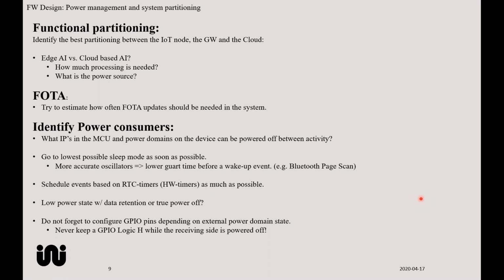So it makes a very big difference, and especially over years of operation, it makes a significant contribution to the overall power consumption. Now, these states will change depending on whether you enable a function or not. So if you enable function X, you need to define the GPIO pins in one way. And then when you power off that function, you should, of course, not forget to reset all these pins and interfaces that you have in that.